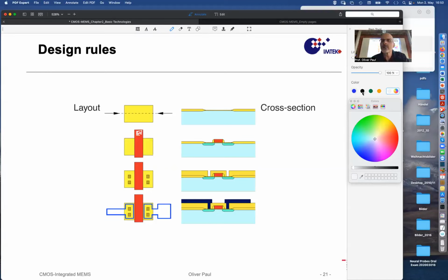And let me go back to some other colors. And then for the source and drain contacts. Now here I show you this example where this insulation silicon oxide, yellow, the silicon oxide has been opened with some vias, and now the vias have been filled, and on top there is this metallization. Those vias, those holes are in the form of these little rectangular or square holes that are cut, etched vertically into the yellow silicon oxide.